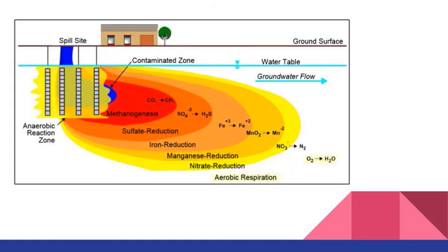And here is a figure that shows the redox zones' response to a typical plume moving through an aquifer. We are able to see distinct redox zones are built, and there are anaerobic reactions that happen right near the spill. While the redox reaction is continuing, aerobic reaction eventually happens. Therefore, in some cases, enhanced aerobic remediation will have additional oxygen added to keep the efficiency.